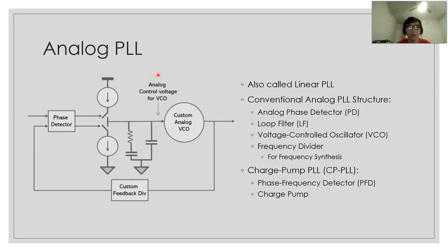Another modification of the phase-locked loop is the charge pump. Basically, the phase detector outputs two signals, up and down, and these two signals control a thing called the charge pump. It will inject more current into the filter if up is on. Otherwise, if down is on, it will drain the current out of the loop filter. This block adds accuracy and reduces noise of the output signal.